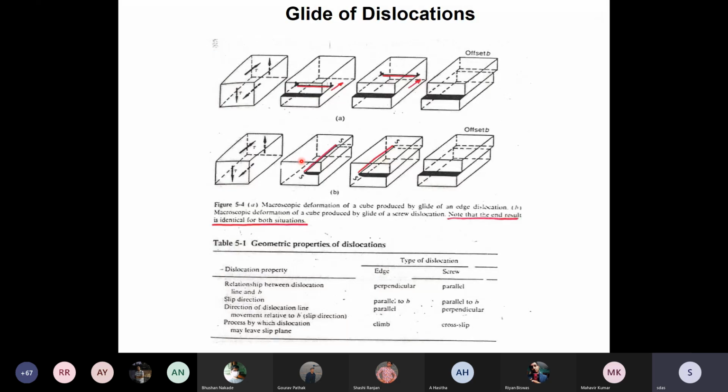So try to do this experiment. Get a metallic paper clip, meaning no plastic coating on it. Straighten it up like a wire, twist it back and forth, and it snaps. You can take aluminum wire, steel wire, or copper wire, and you get the same results. Every time you twist, you introduce a lot more dislocations in it.